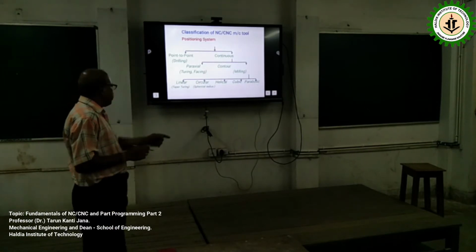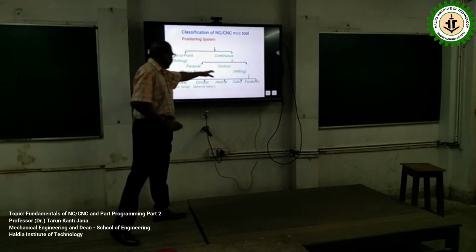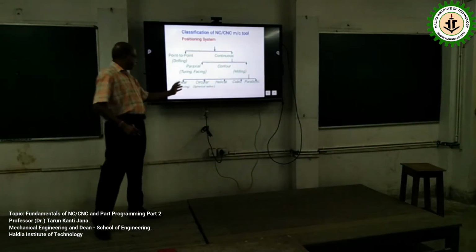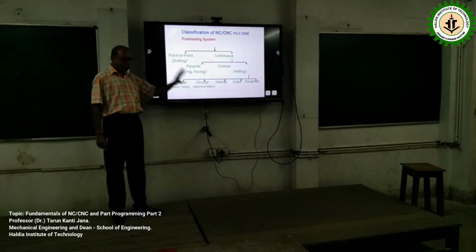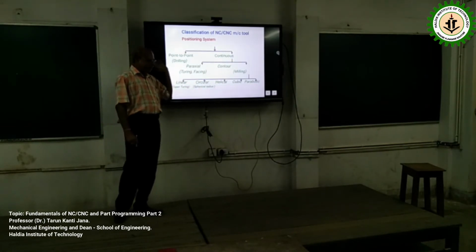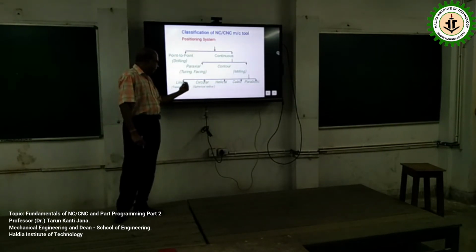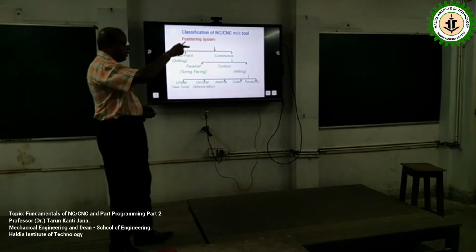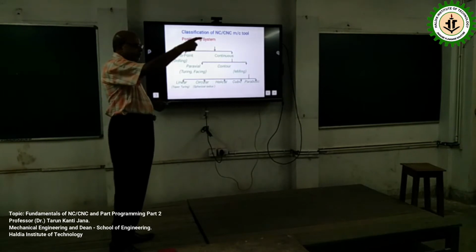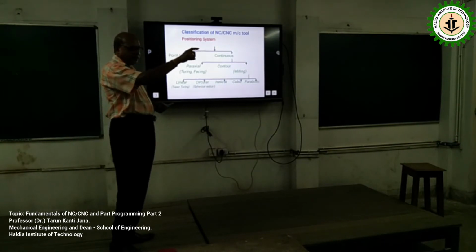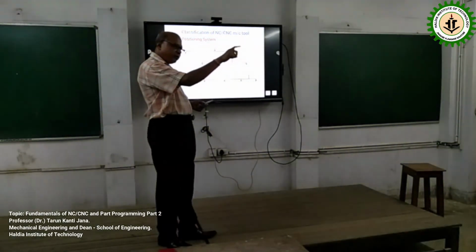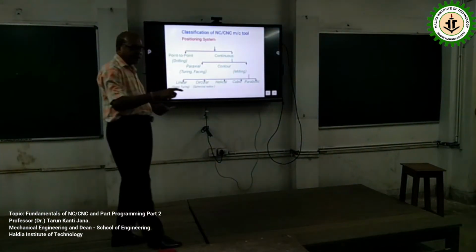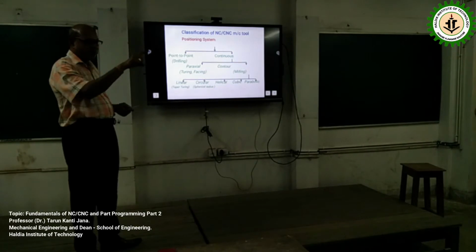The operation you are carrying out in the CNC router or PCB milling, those are basically milling machines. Contour control can be subdivided again. It can have five different variants. These two are popular and are also available in the machines in the lab, that is linear and circular. Some portions are straight line, some portions are arcs, and some combine both.